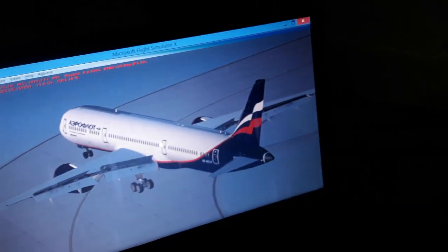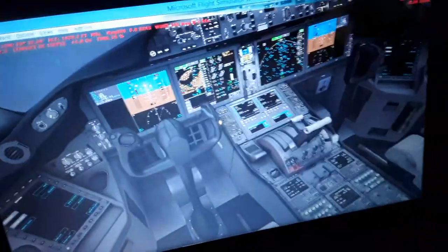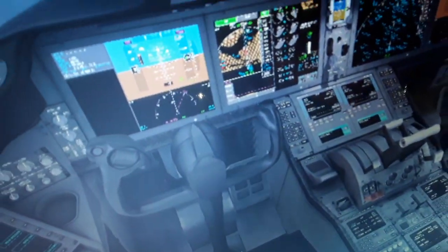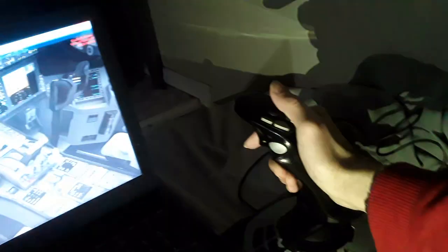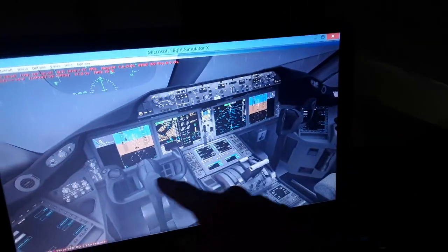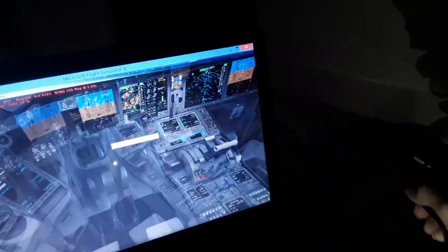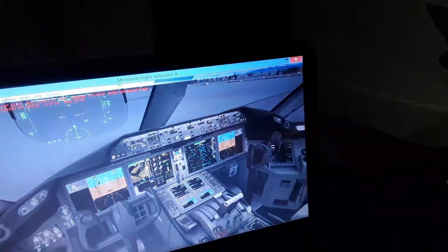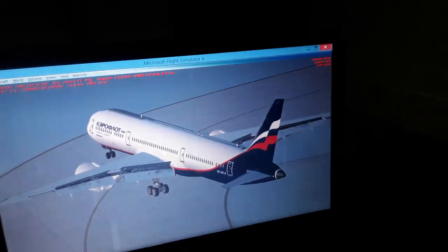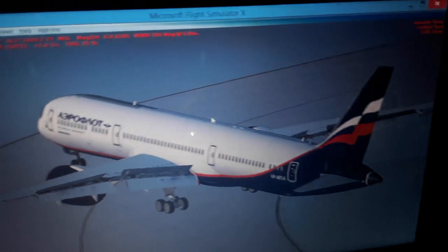It's done automatically. So you can see here inside the airplane, we have the rudder pedals of the Boeing aircraft, similar to the Airbus or the Embraer or the CRJ aircraft. So we can control left and right turns with the rudder, the vertical tail rudder when we fly, or the rudder and the nose wheel when we take off on the runway or land. Also the nose wheel steering on the ground, so we can control the nose wheel only when we are on the ground, like in the taxi.